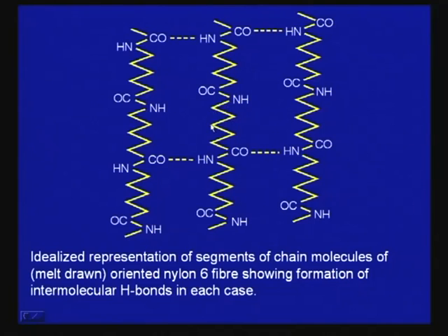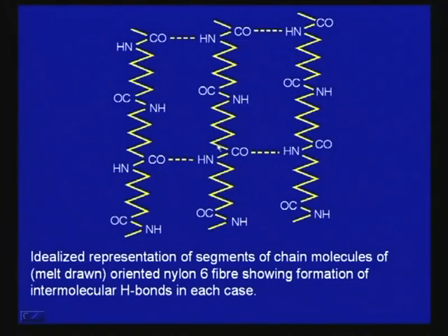Now, here you see, if the units present between two polar units are an aliphatic chain, what happens? Aliphatic chain is flexible. So, you can get a flexible structure. Now, if you want to have a rigid structure, then you can place one phenyl ring here. You can have a polymer exclusively made of aliphatic units along the backbone, or you can have exclusively aromatic units, or you can have a mixture. That means you have the tailorability option. You can design and synthesize a polymer having both aliphatic as well as aromatic units in one backbone chain, as you like.